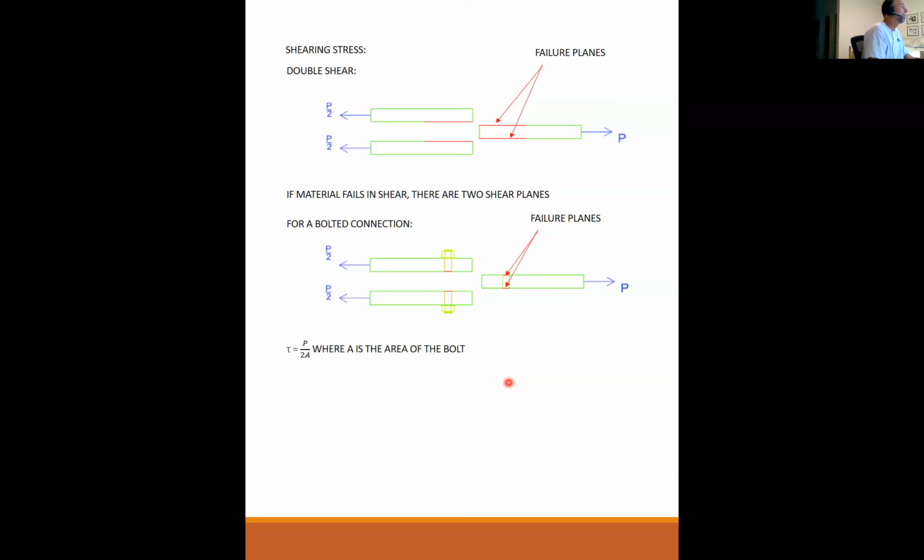And there's a lot more. But just for example, dead load could be 1.2, live load is 1.6, soil load is 1.6, seismic loads, coincidentally, is just 1.0, and wind load now is just 1.0.